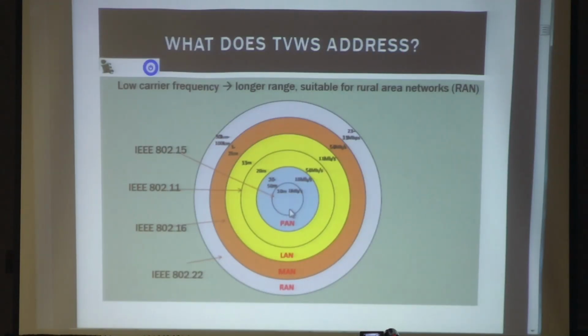So things like personal area networks or Zigbee, for example, the 802.15 standards that are meant for very low data rates and very local distances, within tens of meters. Those would fall into the 802.15 standards, and they have transmission distances up to 50 meters. And the data rates can vary from 1 megabit per second all the way up to 10 megabits per second.